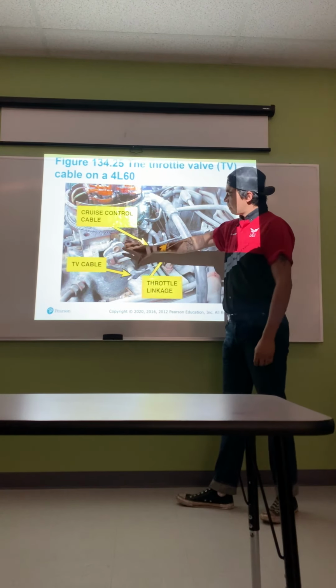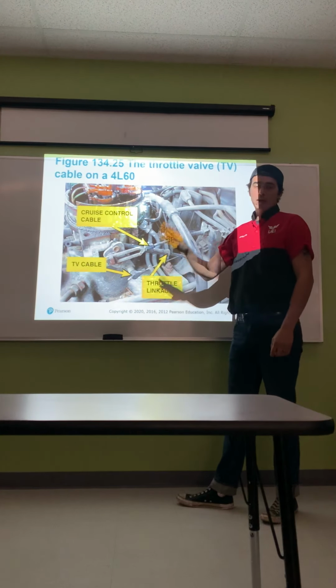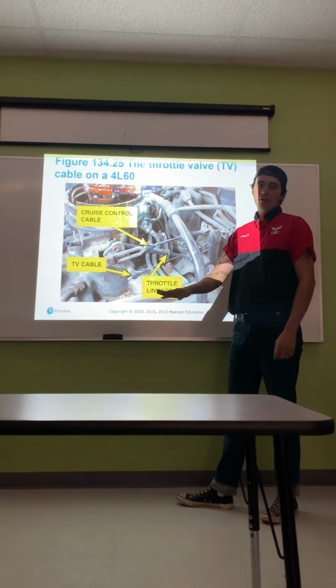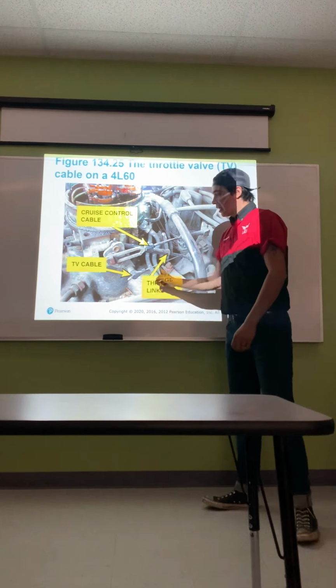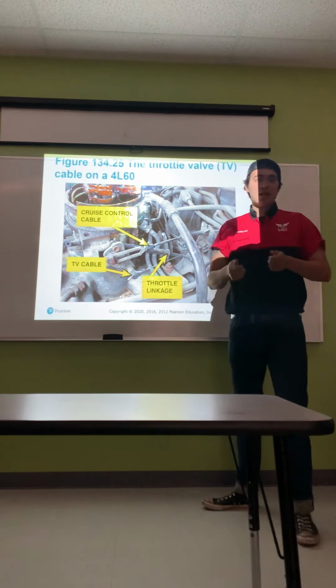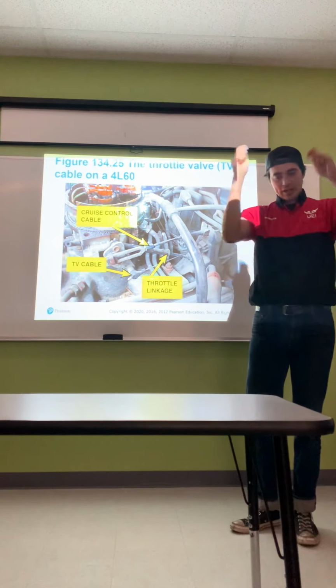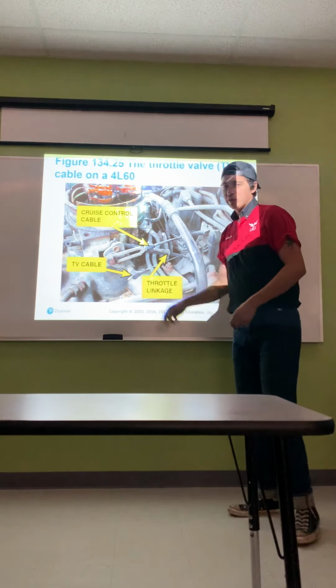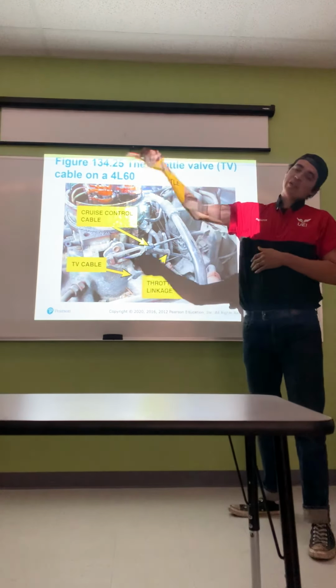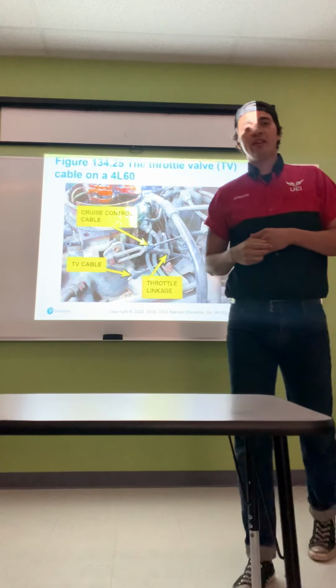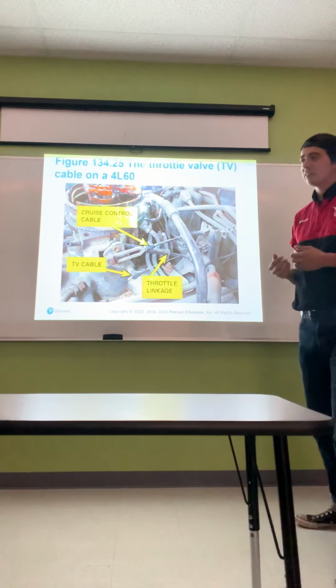When you apply pressure to the pedal, when you go full wide open throttle, it's sending a signal manually by using this cable, and it's saying, hey, it's kind of like a horse when you whack it like that. It's like, hey, we gotta go. This is what that cable is doing. It's actually pulling manually inside, engaging the valve body, which then makes it downshift into a lower gear.